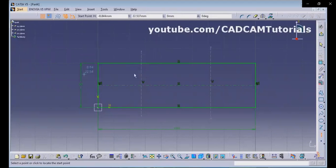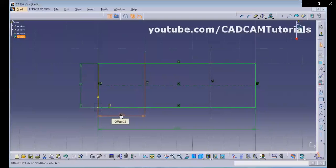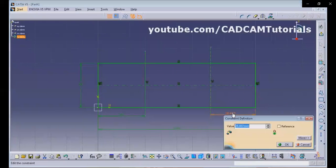Then we will give dimension using constraint. Click on constraint, click on this line and this axis and give it 30. Again constraint, this line and this axis, again give it 30.